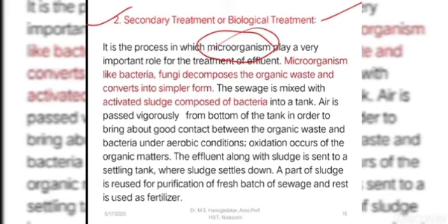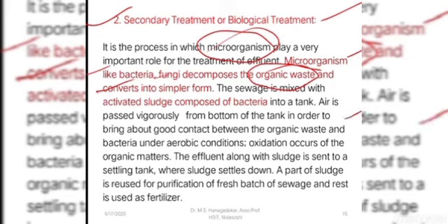As you know, the microorganisms may be like bacteria, fungi, etc. These microorganisms are going to decompose the organic waste present in the wastewater and convert it into a simpler form. Here the activated sludge is sprayed over the tank and air is passed vigorously from the bottom of the tank. So there is very good contact between the air and the organic waste present in the water,